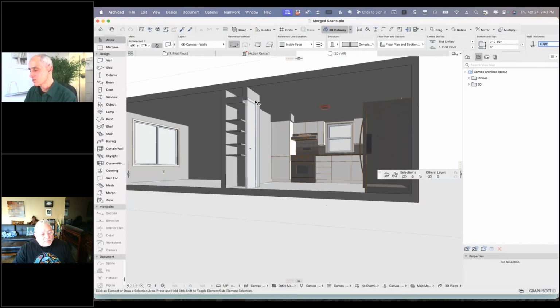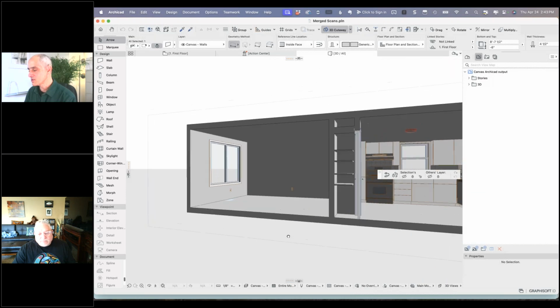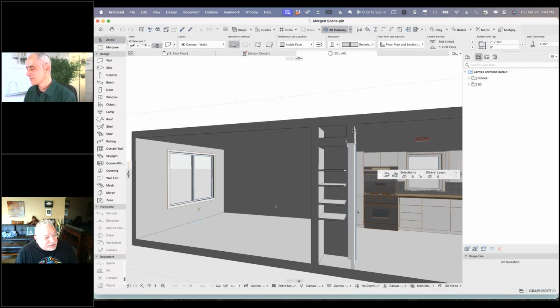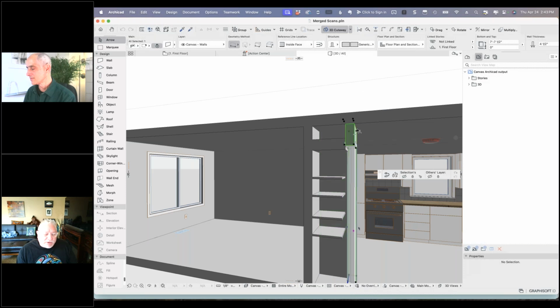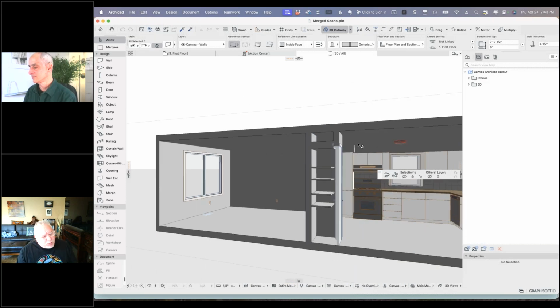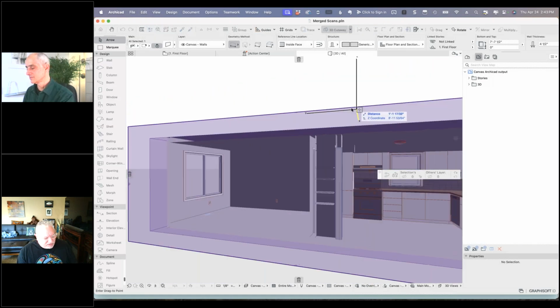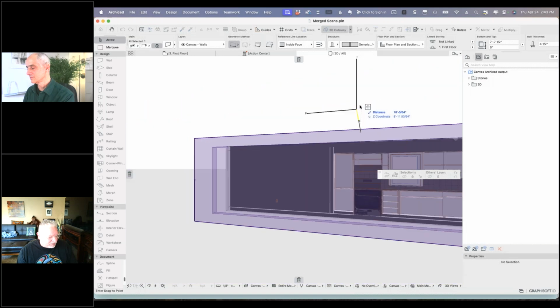So that's an odd measurement there. And this one's 4.5. That's an exterior wall. Do you have any issues with figuring out what it's doing? In this case, when the house was built, they were doing the exterior walls with 2x4s. They typically default to 2x6s for exterior walls, unless you tell them in your sketches or in a note to use 2x4 for the exterior wall.